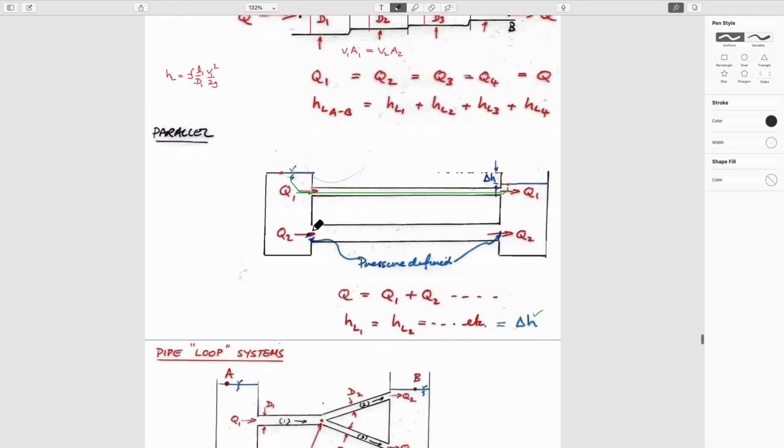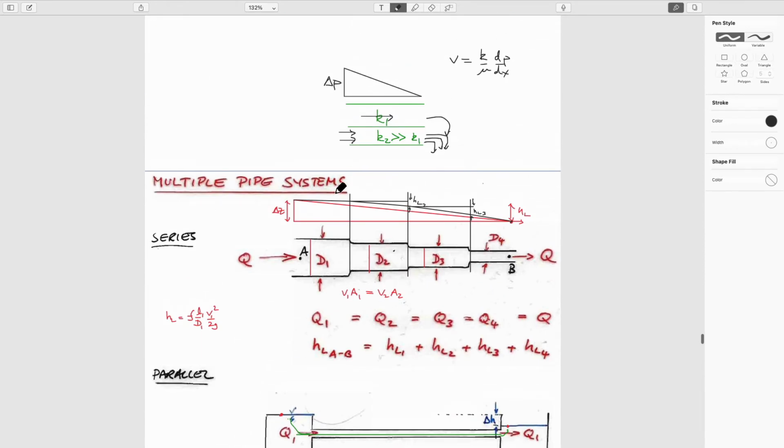And so it's a manifestation that the flow rate is some that comes through one of them and some that comes through another one. If this happens to be a big pipe or a high permeability, then the flow rates would be that. Conversely, if you have a system that looks the same as we had before, with exactly this arrangement of permeabilities, but you're pumping it upwards by having a pressure gradient that goes upwards, then to get flow out of this bed, which is highly permeable, it has to go through this bed.